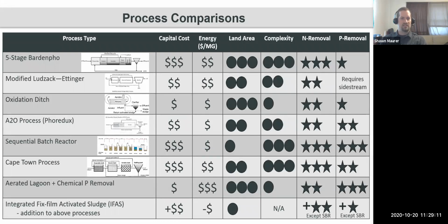And similarly, oxidation ditches are particularly well set up for an MLE type process, as they already have an oxygen gradient set up. You have a high oxygen content right by the surface aerators, usually some kind of rotor system, or maybe a subsurface mounted propeller type aerator. As you move away from that, you get into an anoxic type zone, kind of shown in the diagram there. So they're already set up to be used as an MLE process.